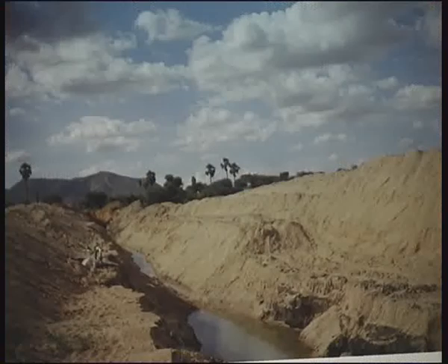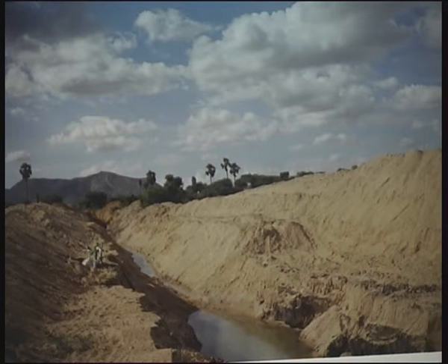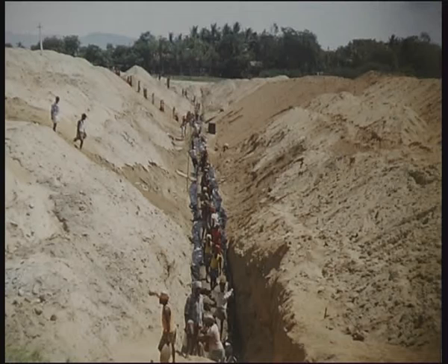Next item is subsurface dam. When we say subsurface dam, it means that a dam underground has to be constructed. That would be usually below the bed of the stream. It is a sort of a dike. The purpose of the subsurface dam is for preserving the groundwater on the upstream side of the dam.